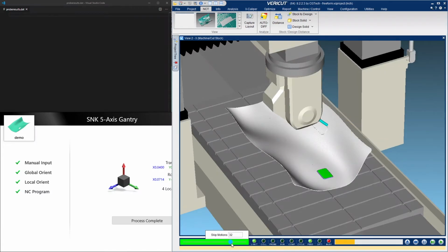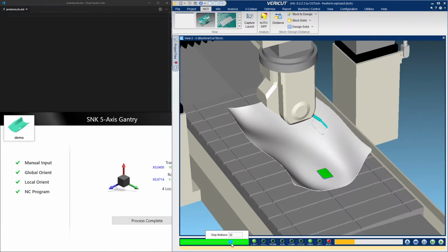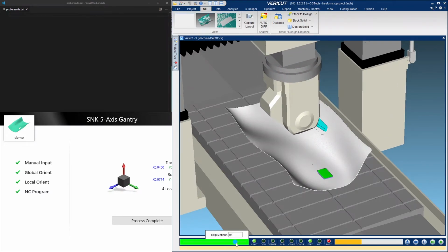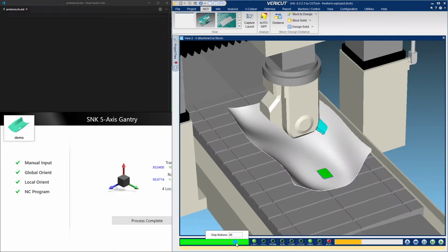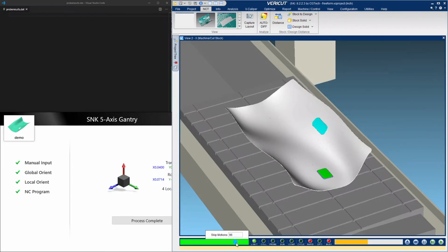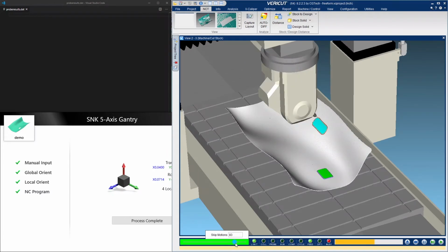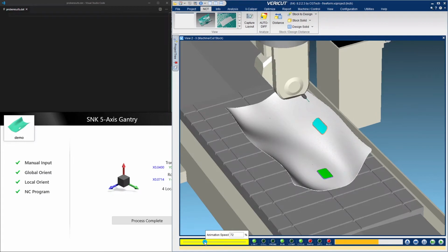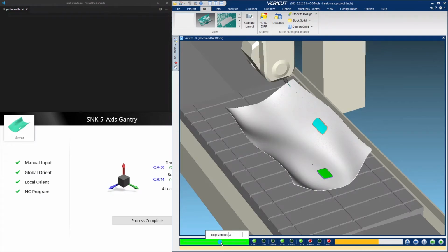We will then do the same thing for the second pad, color the top surface using the 1.5" ball end mill. Blend that in with the 1/4 inch ball end mill to the existing contour. We'll drill the holes all the way around the part using a 1/4 inch drill.